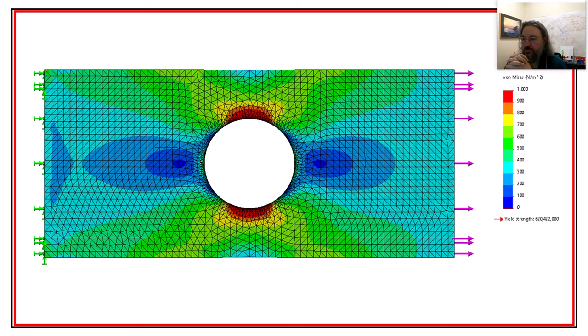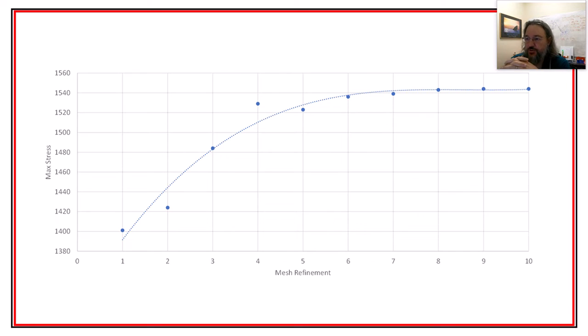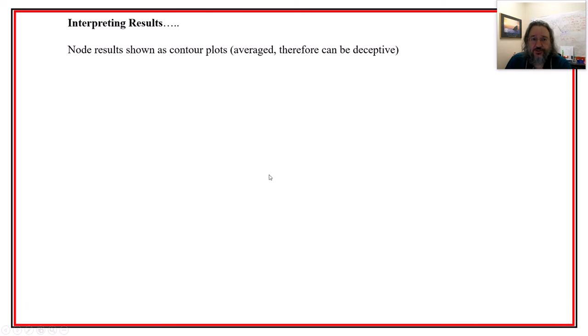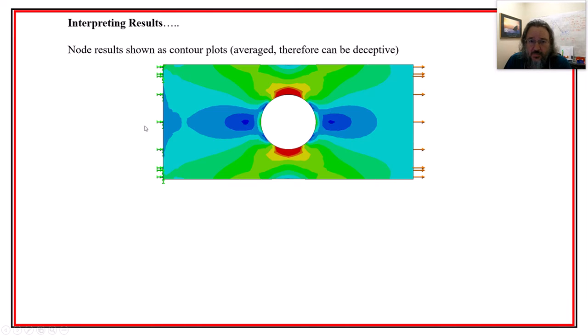Okay, welcome back to class 10, and this is video 3. In the previous video I talked about mesh refinement and how we could converge to a solution, and in many cases some scenarios won't converge. We could actually have a really hard corner that creates a singularity which sends meshing up into the atmosphere. So let's talk a little bit about that, mesh results, right?